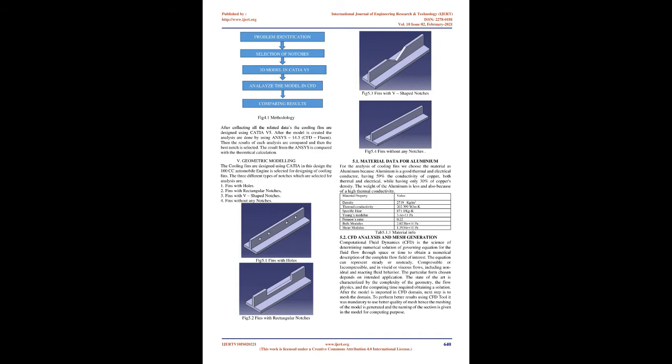Literature review. Deepak Gupta, Wankhede S., Ref. 1, Design and Analysis of Cooling Fins. In this paper the author tells about cooling fins being used to increase the heat transfer rate of a specified surface. Engine life and effectiveness can be improved with effective cooling. The main aim of the project is to study and compare the 100cc Hero Honda motorcycle fins and analyze the thermal properties by varying geometry, material, and thickness. The analysis is done using ANSYS.